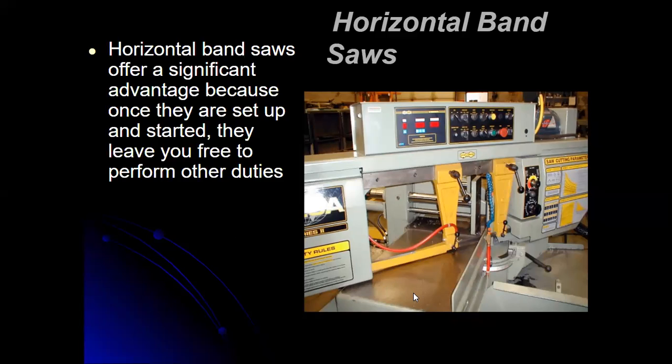to perform other duties. So mine has an automatic stop on the bottom. When you're done cutting, the blade will stop, it'll shut the motor off. You can then lift it up, slide the next piece in, start it, you can walk away, come back when it's done. I generally don't go too far away because if something does happen, I need to be able to shut that machine down quickly. But it is nice because you don't have to sit there and babysit the saw for every second it's cutting.